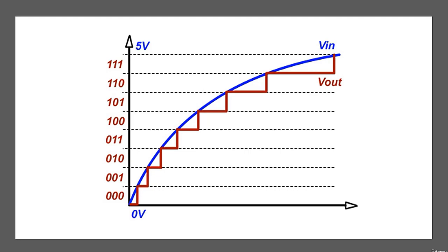The number is very usual because when you have a 3-bit digit from 000 to 111, it gives you a value 8, or basically 2 raised to 3 will give you 8. Now if you have an 8-bit ADC, then the maximum number of results you have is 256. If you have a 10-bit ADC, then you have 1024 results. If you have a 12-bit ADC, you have 4096 total number of results. The higher the resolution, the better you can differentiate between the applied voltage levels.